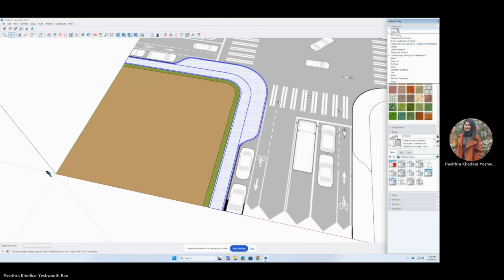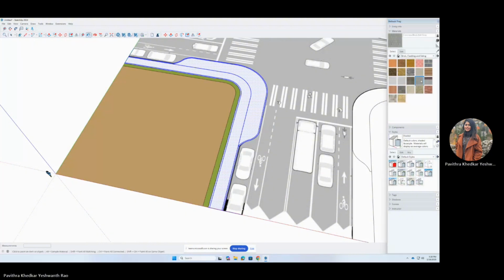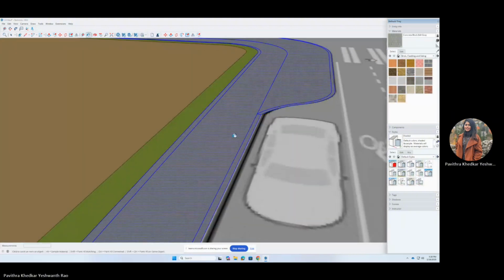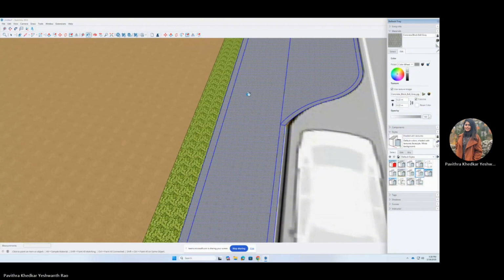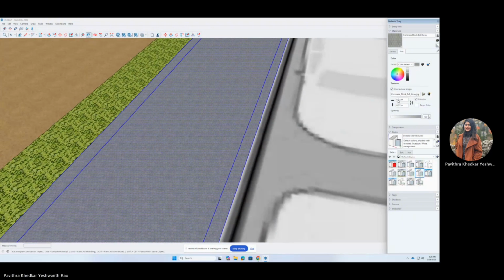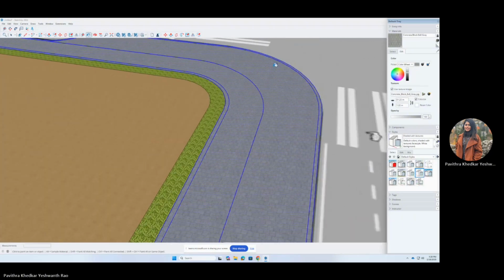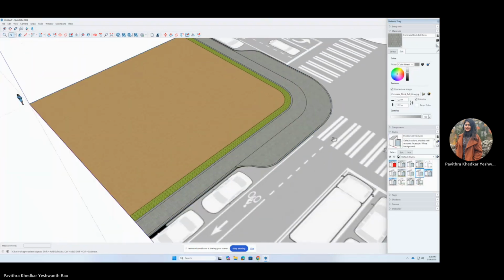SketchUp's built-in material library is a fast and lightweight palette, but it doesn't look very realistic. For adding more materials, explore Pinterest and search for seamless textures for SketchUp or Photoshop. You can save these in a folder that you can revisit and use later.